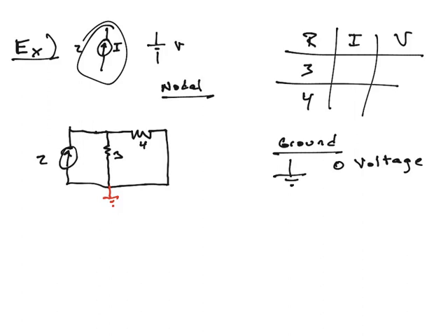And I'm going to say, okay, notice where the current source is located. I could choose this point to be a node if I want. But notice all that's there is this bunch of wire over here until I get to this split off point. And so that wire is really nothing to me. So that's not a good place to choose a node, because really all of this is one big node.